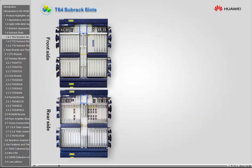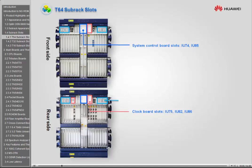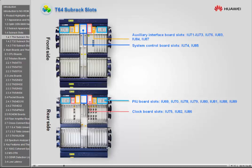The system control board slots are reserved to provide for SCC board 1+1 redundancy. The clock board slots are reserved to house an STI board and two STG boards in 1+1 redundancy. The PIU board slots are reserved to house 4 pairs of PIU boards, and the PIU boards in each pair are in 1+1 backup. These auxiliary interface board slots are reserved to house EFI, AUX, and ATE boards.